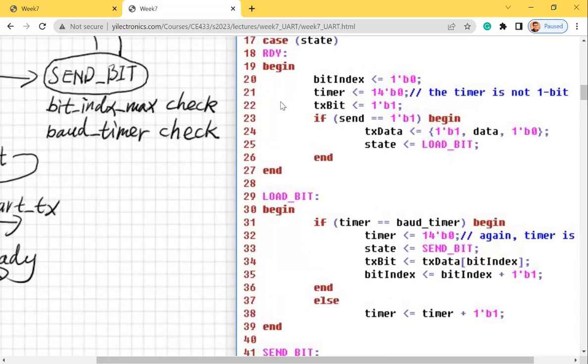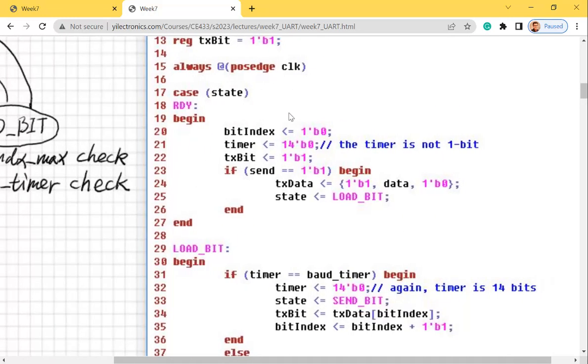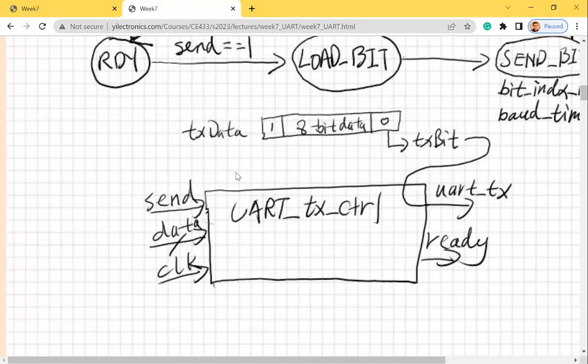Ready, which is the first state. It's waiting. So the data, do you know if the data is ready? Is the TX module able to tell if the data is valid or ready? Is it responsible for telling if the data is good data to be loaded or not? No, whatever is sitting there is going to load it. It can be 0, it can be nothing.